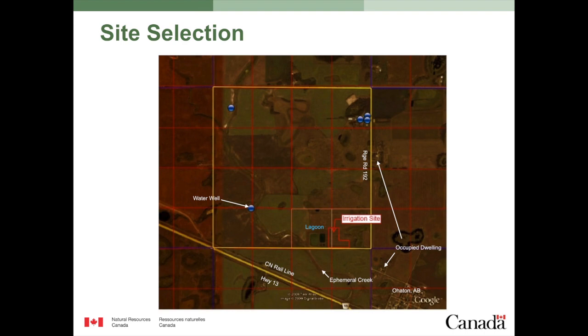There's also a few other requirements. They're more related to the biosolids, but depending on the regional engineer we were dealing with, we were held to some of these. 200 meters from schools, 200 meters from cemeteries, playgrounds, parks, and campgrounds. Some wanted groundwater sampling wells, other ones didn't want groundwater sampling wells. All of these things come into play when you're deciding on where you're going to put this. So that's why you have to be discussing this with your regional engineer or with your regulator, so that you don't get caught out with one of these parameters hampering your site selection.